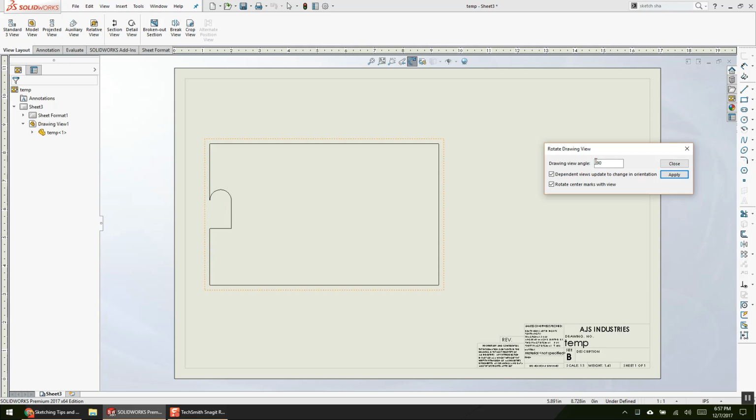In a mill, I'm going to put it in a vise like that. Every time, guaranteed. I never hold material in the mill on the small ends the long way. Ever. Virtually ever. Because nobody puts their vise on the mill sideways, right? Unless it's a really special thing.